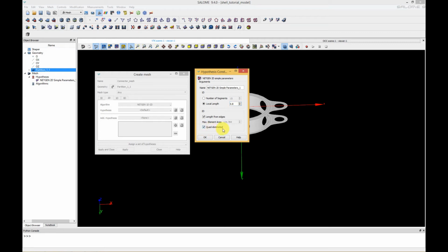It's important when you're doing finite element to check this box here, because it ensures that you have the most quads possible in your mesh. It's important because when, for instance, you are dealing with shells, quad shell elements behave way better than triangular shell elements. So in SesamX, for instance, our quad shell element is the MITC 4+, and it's a very good element, and our triangular shell element is the MITC 3+. It's also a good element, but the MITC 4+ is even better. So that's why it's important to ensure that you check this box.